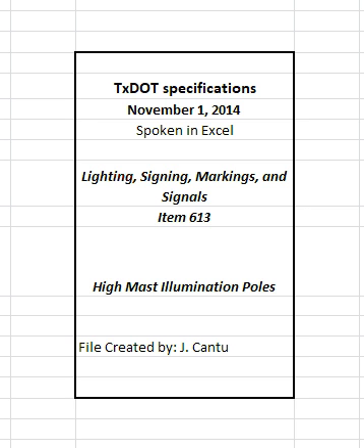Ensure splices are a minimum of 90% or a maximum of 110% of the planned lap. Mark the 90% and 110% locations before assembling the pole. Obtain written approval from the department for splices that do not meet lap tolerances before erecting the pole.